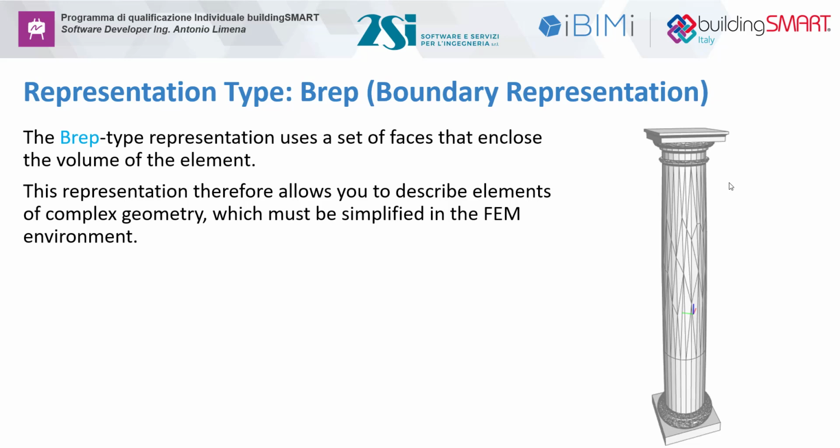And here I reported the example of this column on the right, that is, let's say, an old style column, an architectural column with a large amount of details, and that, of course, in a FEM model aren't that important. So in a FEM model, I don't care about this section variation on the height of the column, all the elements, the capitals on the top and the bottom.